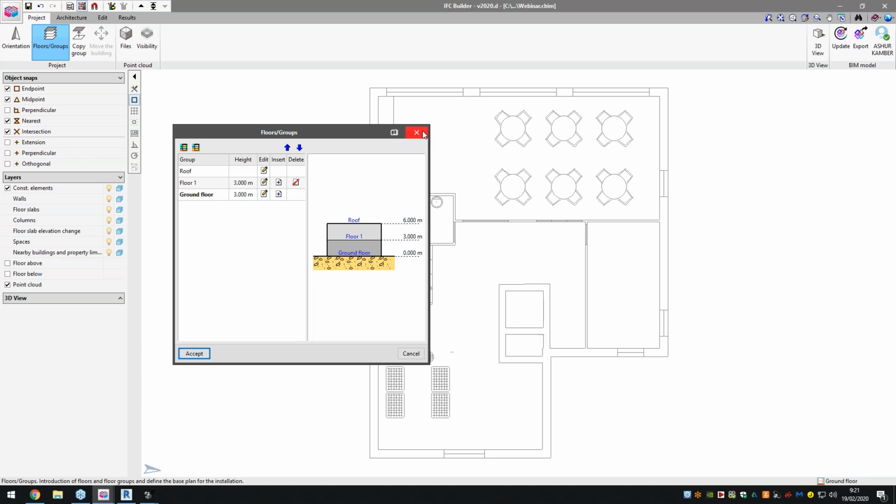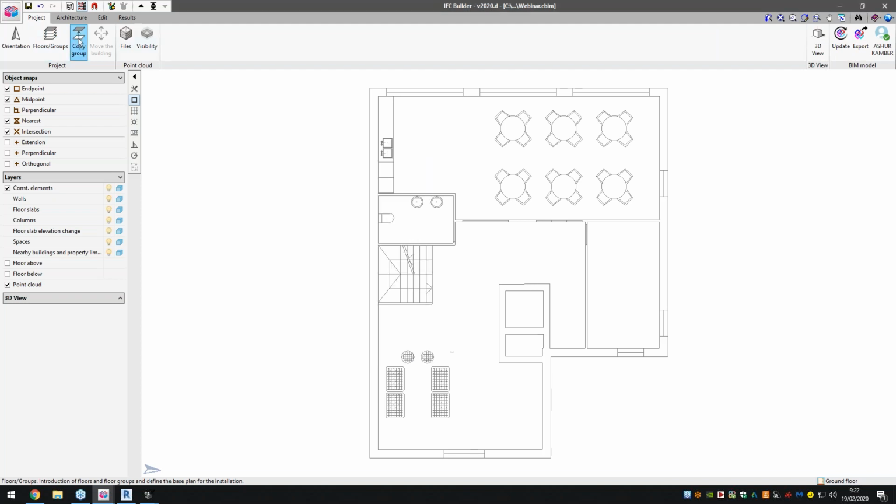Sufak asks, now it's a specific question, whether we can make different heights in the same floor, like a part of the floor is 5 meters high and the other is 4 meters. What you need to do, just in short, is create 2 separate floors and define them as such as well. So the program understands that. But of course, I'll go into more detail about it a bit later if that doesn't answer your question. But moving on.